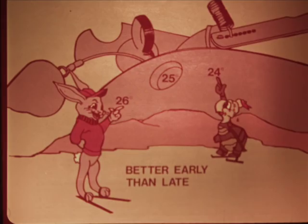Here are a couple of tips on timing. 1. A feeler gauge adjustment of the points isn't always accurate enough. That's why you should use the ohmmeter to measure the exact point when they break. 2. If you can't get dead on to 25 degrees before top dead center, it's better to go 26 degrees than 24. A retarded spark makes the engine run too hot.